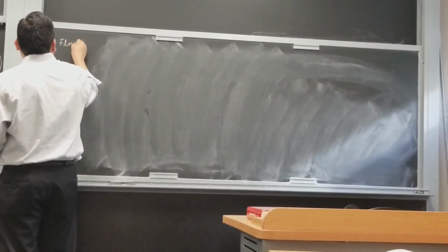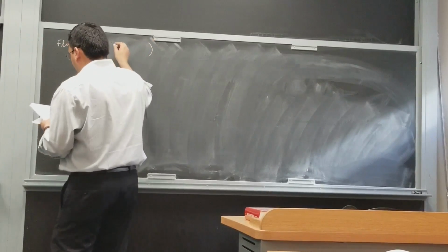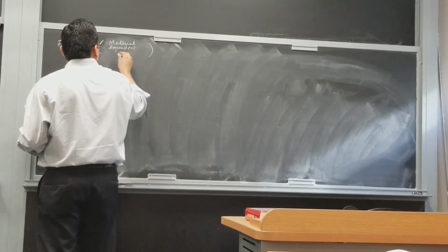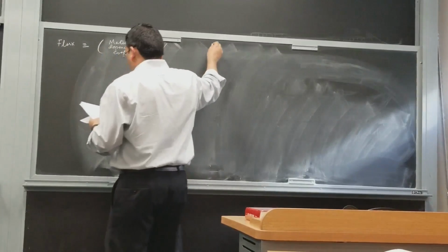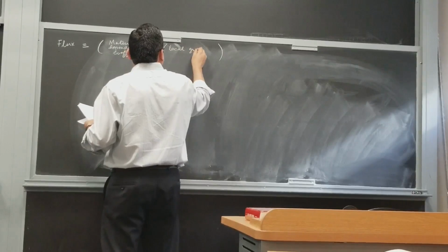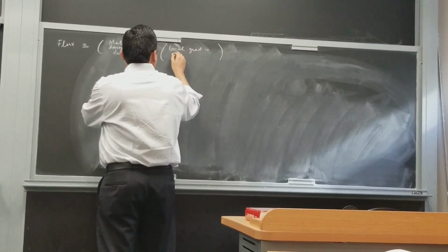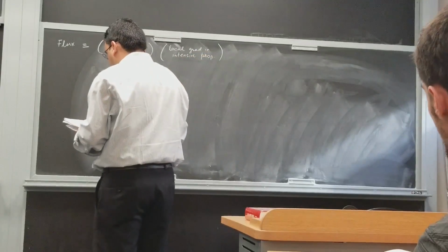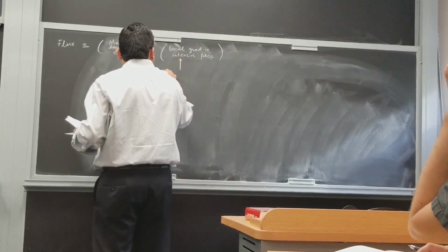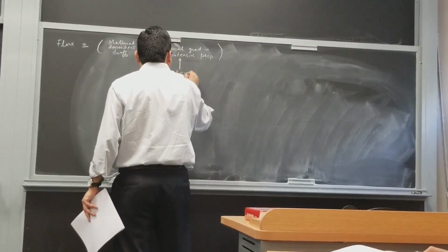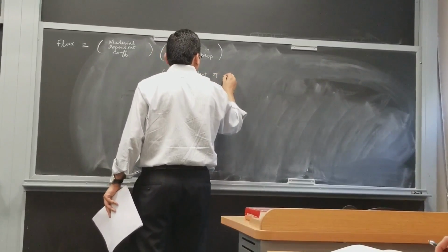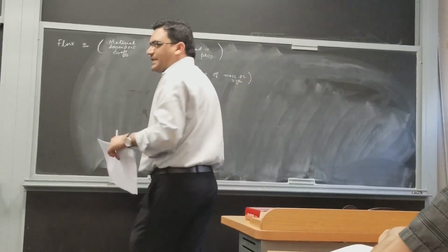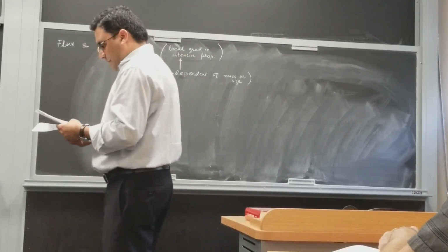So what flux tends to show is that flux is equivalent to a material dependent coefficient times a local gradient in intensive properties. We're going relatively slow today, but we'll speed up. Again, from your thermodynamics, you should remember that intensive means it's independent of mass or size, as opposed to extensive properties that depend on mass and size. Right? So that's what we said so far.